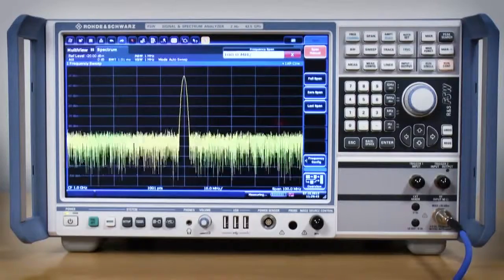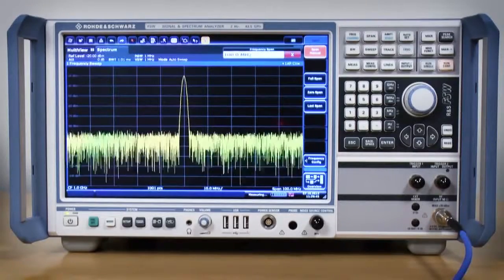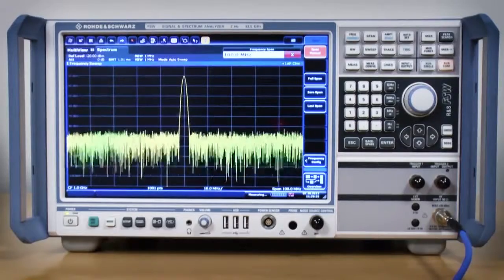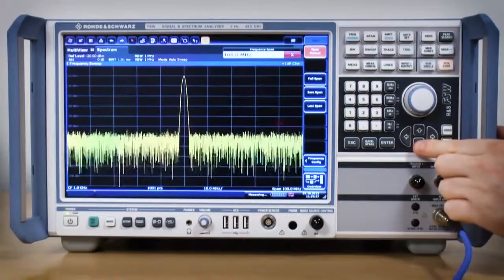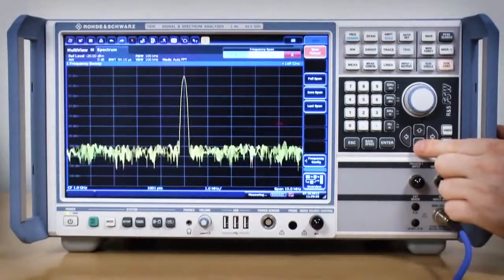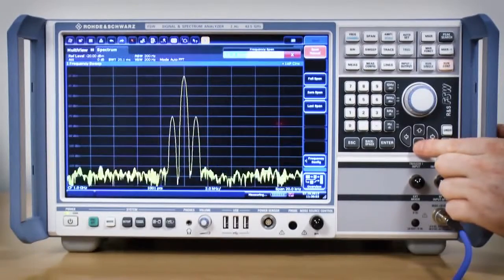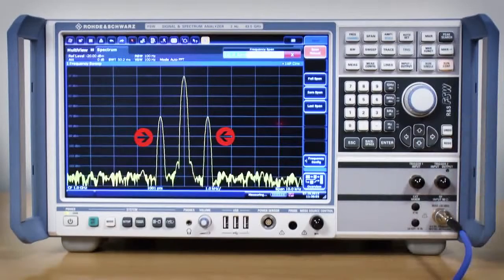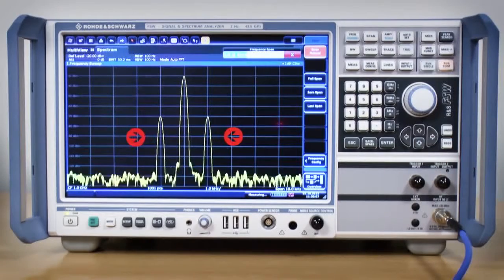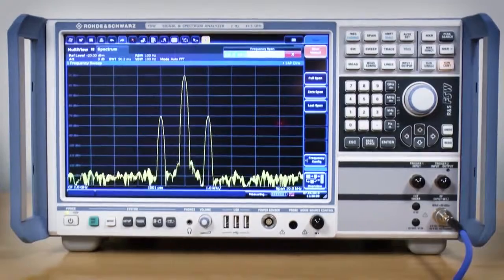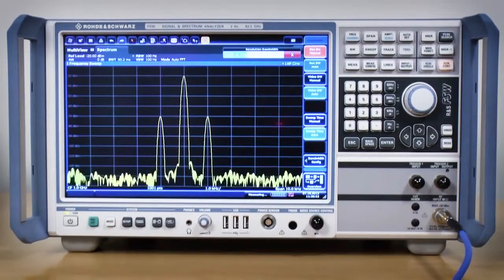Here we see an amplitude modulated signal on the analyzer screen, but in order to see the sidebands, we need to adjust the span. As this is progressively reduced, the spectrum analyzer scans a smaller bandwidth and the sidebands are seen. In reducing the span, the analyzer has two controls linked together. The first and most obvious is the span, the actual band that has been scanned. However, it also reduced the resolution bandwidth.